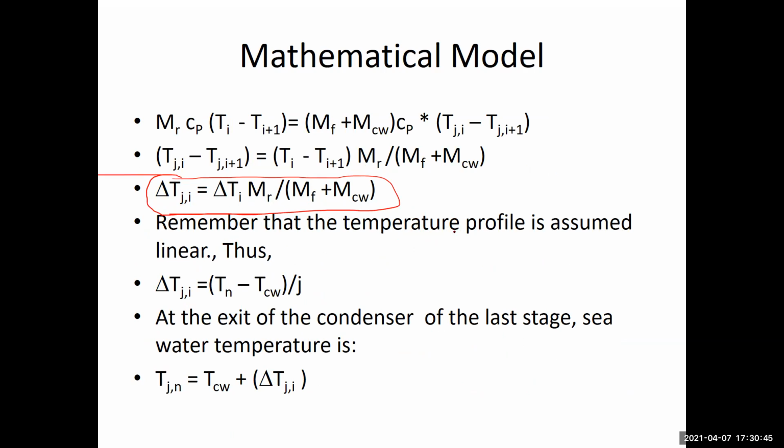And the relation between delta T, if I'm talking about the heat rejection section, which is made up of 3 stages: the delta T here and the delta T across these stages are not going to be equal, but they are related by this equation as we see it here. And definitely the value of delta TR is going to be different.